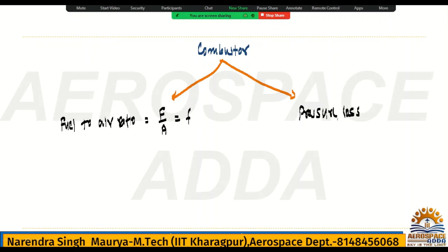It will stick over the air particles and go outside, because you have not mixed properly. With the air only, it will go outside without burning. For that reason it is called residence time. So in the combustion chamber, the air and fuel mixture should first of all have proper mixing. Second, residence time means up to what time the air and fuel particles are available in the combustion chamber. Those are the two factors you need to understand.